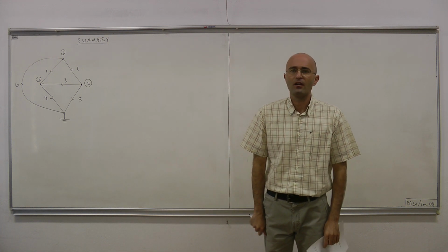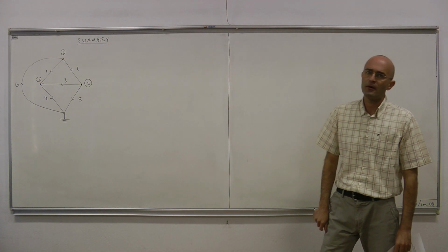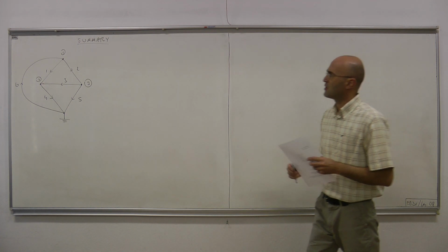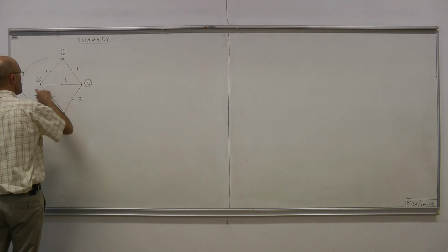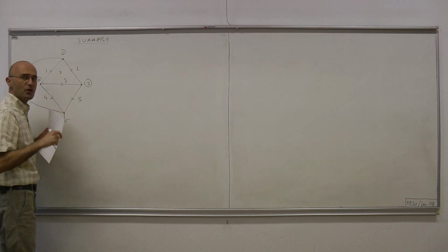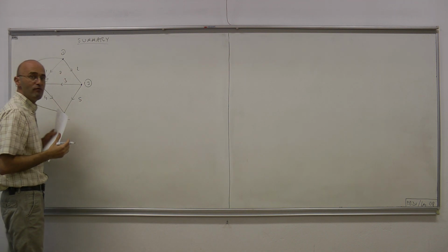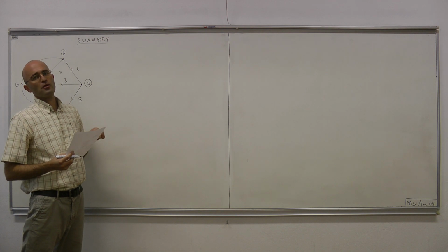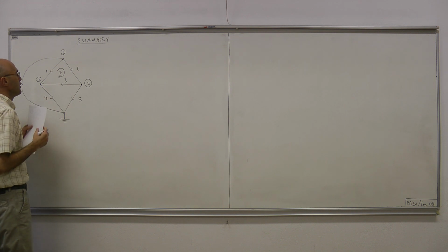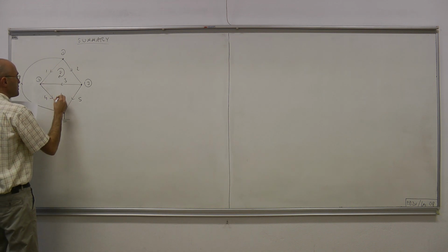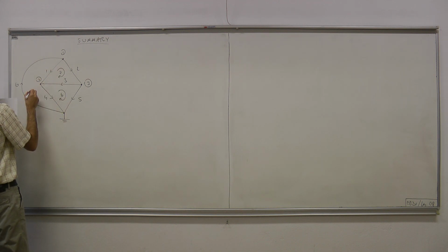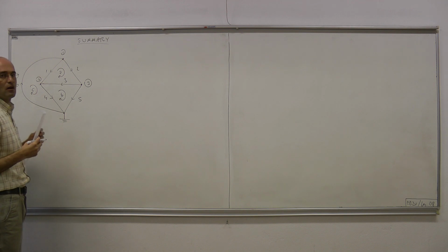And then for writing the voltage equations for Kirchhoff's voltage law, we label the inner meshes. In this case, we have 1, 2, 3 inner meshes. So let's label them as mesh A. Note that a mesh must have a direction, and by convention, the direction we set is chosen clockwise. This is mesh A with clockwise direction. Let this be our mesh B with clockwise direction, and this here is our mesh C, again with clockwise direction.